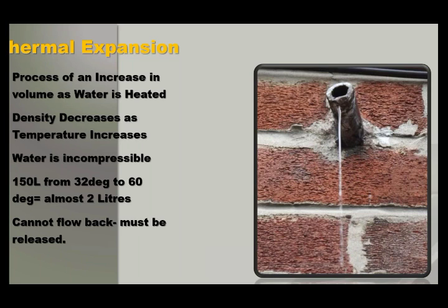To give you an idea, and when I read this fact, it must have been about 6 years ago, about 2 liters of water is displaced by heating a 150 liter geyser from 30 to 60. That is a huge amount of water, a big volume that needs to go somewhere. So obviously, I'm preaching to the converted, but your expansion needs to be properly taken care of.